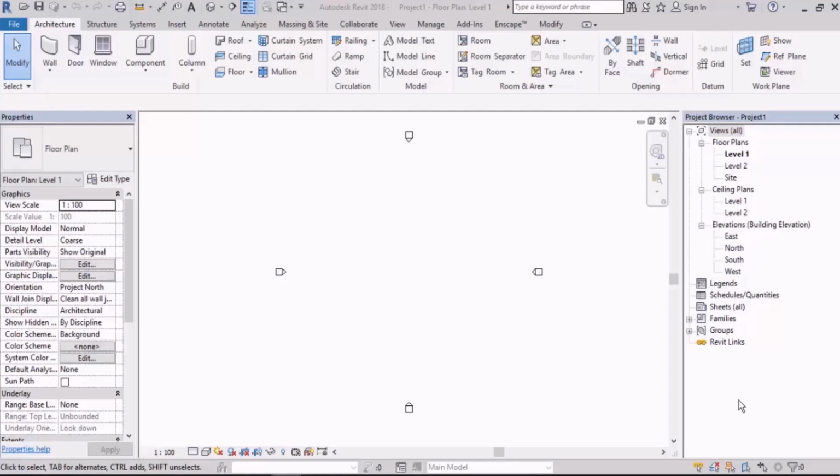So now, in the first place, we're going to learn how we should draw the levels in the Revit software. First of all, we are going to draw the TOS, which stands for the top of slab, as I told you. Right now, we don't know how to draw the TOB, so we leave it for now. And we don't need the FFL either. We will need it in the next session. Right now, we only need TOS, which is the top of the slab.